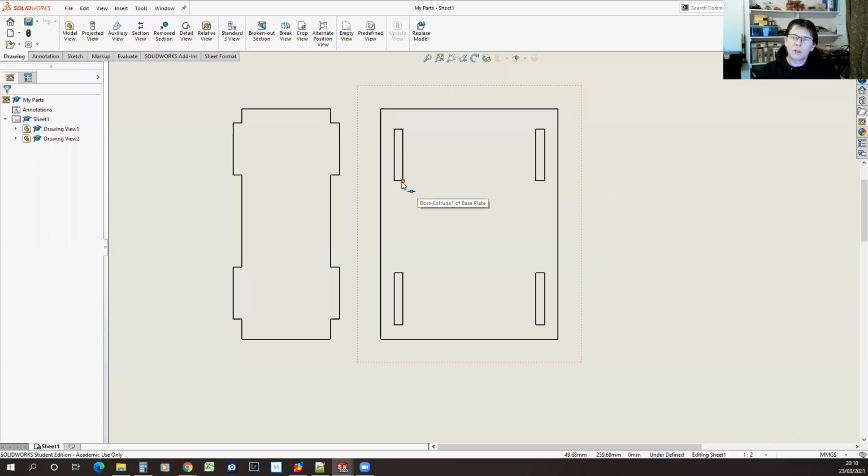So we've got these slots that are 3mm wide to take the width of our material. And then we find that our piece of acrylic is 3.2mm wide. So after I've laser cut it, I can't actually slot it in because my slots are too narrow, because my material is slightly thicker. So kind of lesson one, which I learned the hard way, is measure the thickness of your piece of acrylic that you're going to laser cut before you cut all your parts out, because otherwise your tab and slot parts won't necessarily go together, or they'll be quite loose, depending on whether you've got a thick or a thin sample of acrylic.